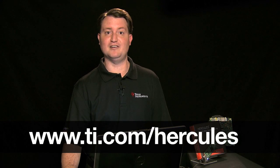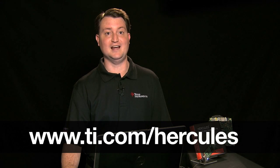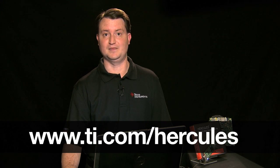Today, I'm going to show you how to configure the general purpose I/O module using HALCoGen, TI's tool for generating initialization and peripheral driver code for Hercules microcontrollers. If you do not already have HALCoGen, you can download it from the Tools and Software area on the website ti.com/Hercules. HALCoGen can also be installed directly from the software DVD that's included in all Hercules USB development stick and